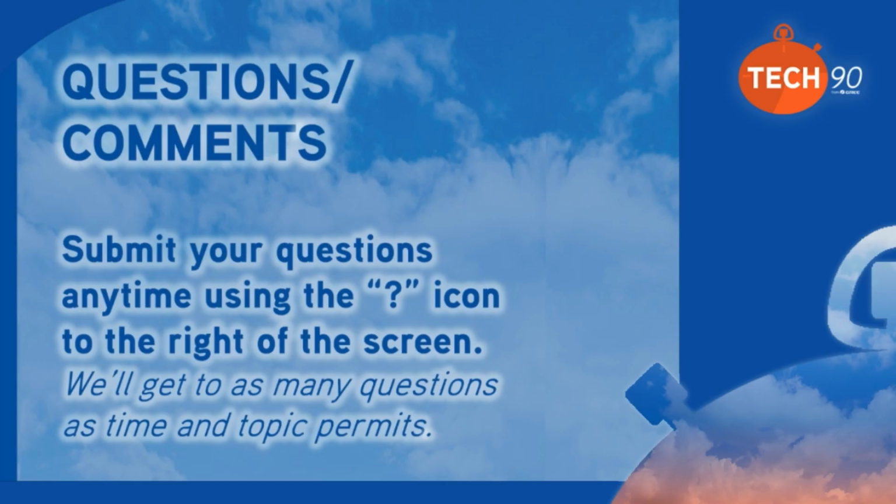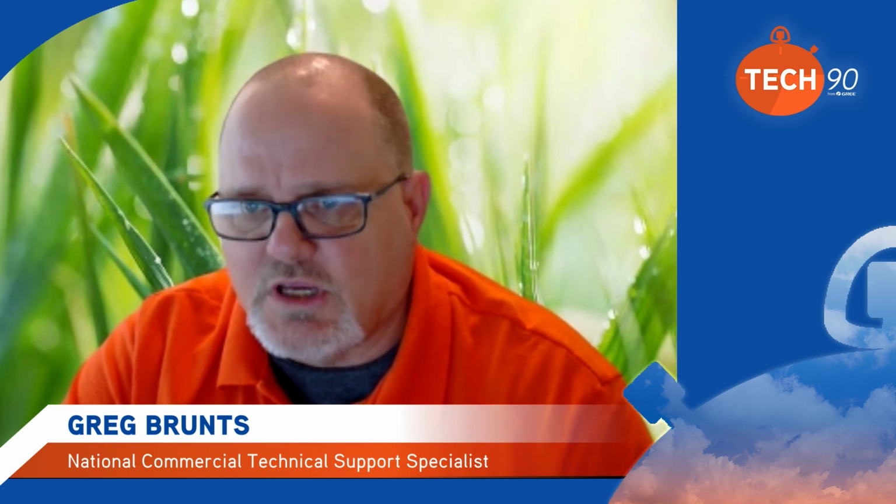Anyway, the question: does the service tool show the EV position on the outdoor unit? Keep in mind, on mini splits, the EV is located in the outdoor unit. Doesn't matter if it's single zone or multi-zone. If it's multi-zone, you're going to have an EV for each indoor unit. If it's single zone, you're going to have the one EEV. Now, multi-pro, not to confuse that, multi-pro EEVs are located on the indoor units, not in the outdoor unit. There are EVs out there, but that is for refrigerant flow for heating mode.